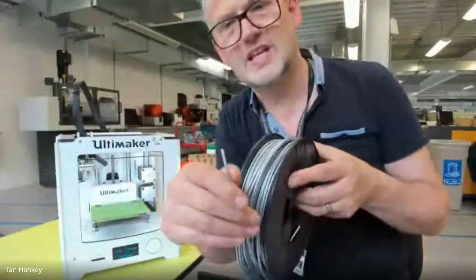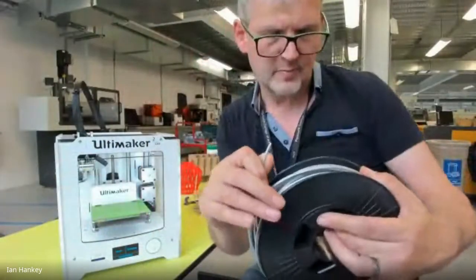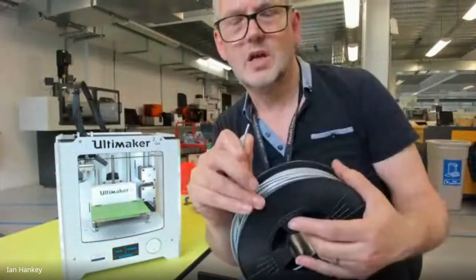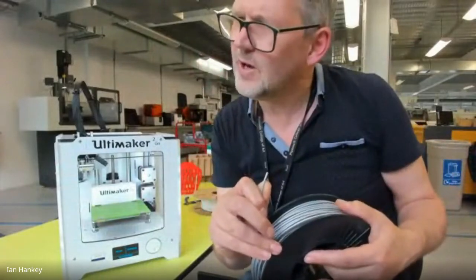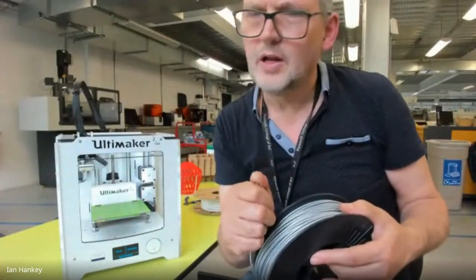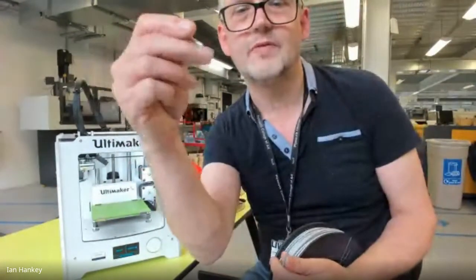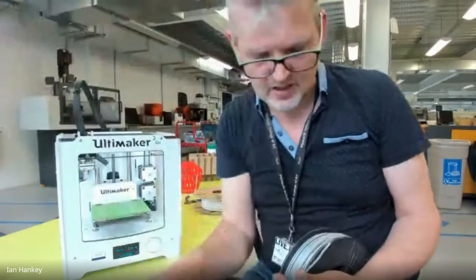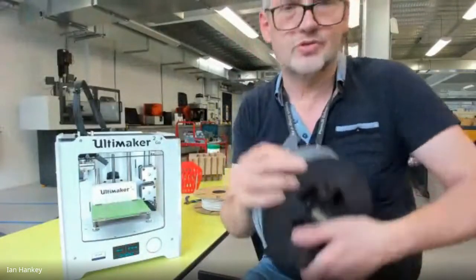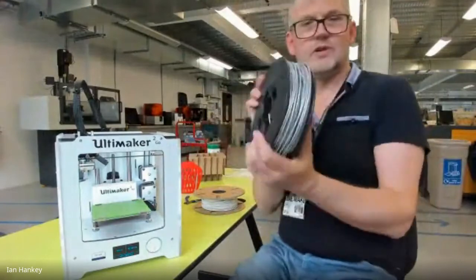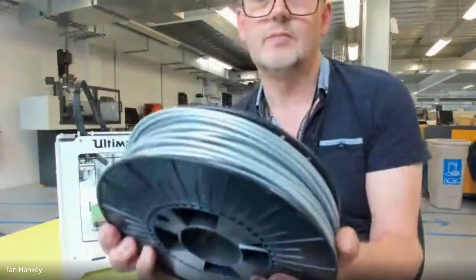There are two different standards of PLA filament size. One is 1.75, is it, Owen? And the other one, as you can see, yes, it's so brittle that it just snapped off in my finger. I'm going to do the same thing here. It's not quite so bad, but it shouldn't be that brittle that it just snaps straight off like that. So it is too old to try to use, but it does give you an idea of the size of the material as we get it.